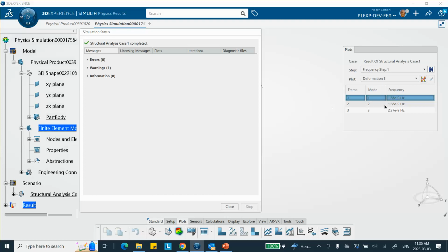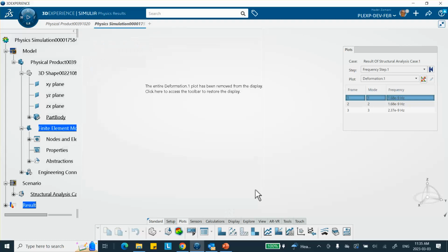Actually, there are no errors. However, look at the values that it gives me. Let's check the warning here first of all. Okay, so there's only 3 of them, no problem. But I really shouldn't have said error. You can see that it gives me values, but there are no restraints, so this is the rigid body mode essentially. 3 rigid body modes because there are no restraints.